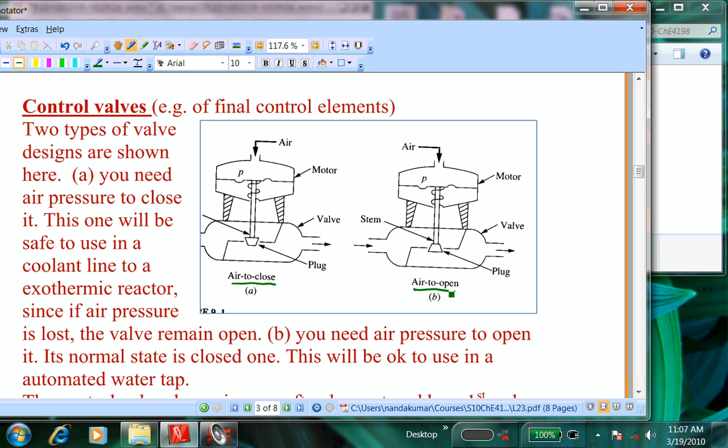Exactly. So everybody got that? It's a pneumatic signal. As I told you, even these control thermostats are pneumatically driven. So you send a pressure, okay? When you pressurize this chamber, it's going to push this down. So it's going to push the valve down. When you push the valve down, what happens to the valve? You have to study carefully what is happening here, because of this shape, as you push down, it's going to close. There is an opening, and through the opening, the liquid will come through this, and through this opening, it's going to come out and go like that.